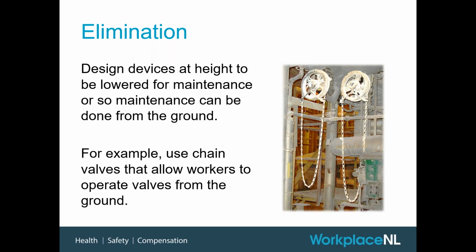If these valves have to be accessed very infrequently, so maybe once a year or once in a blue moon, but if they do ever have to be accessed, especially if there's an element of emergency, like say if you had a leak, you can get chain valves that can replace the normal valve head, and this allows workers to operate the valve from the ground rather than having to again get a ladder or a scaffold out to try to get up there and access that particular piece.